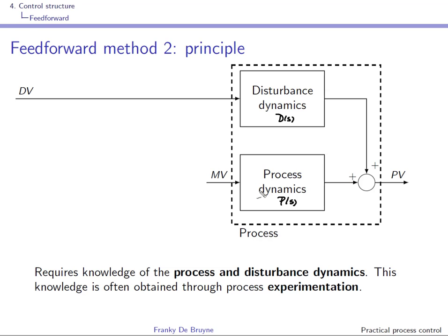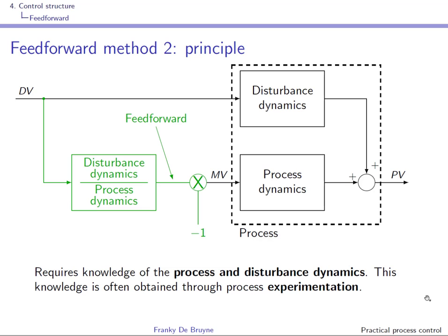What you could do is use IDs similar to what you have done in the laboratory associated to fundamentals of control theory and use, for instance, the function fminsearch in MATLAB to obtain this model. Well, the ideas behind this second methodology leading to a dynamic feedforward are very easy.